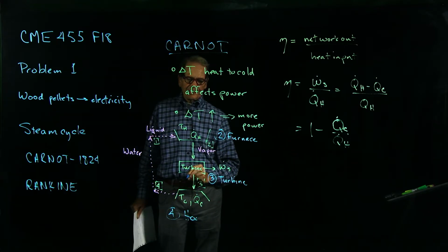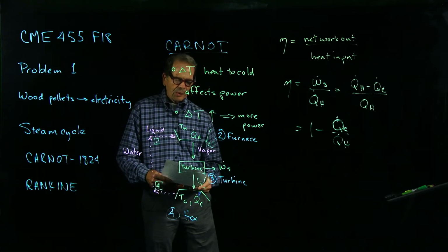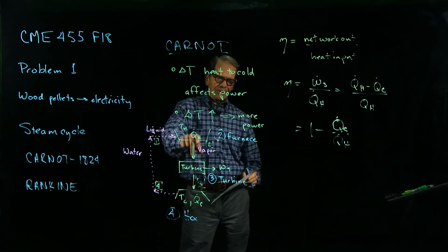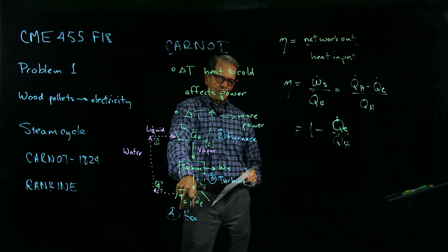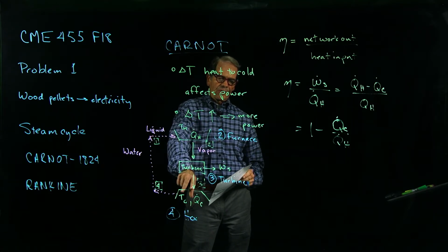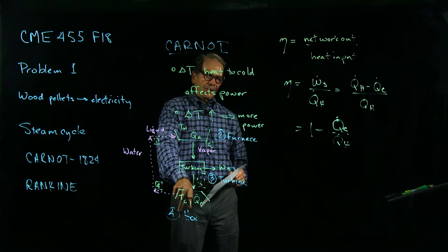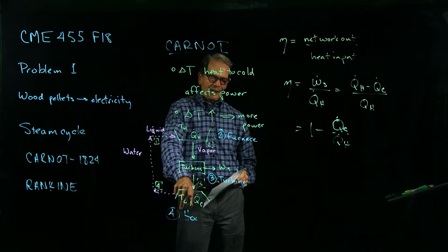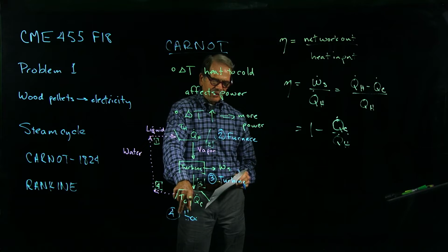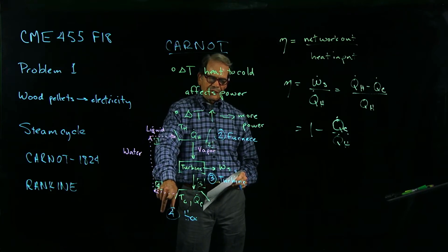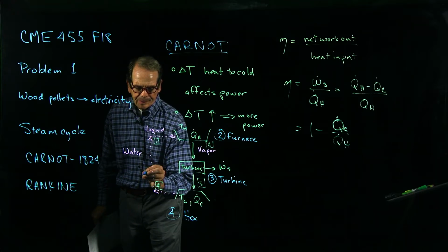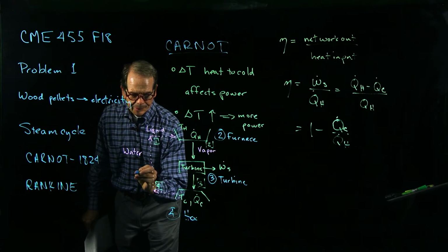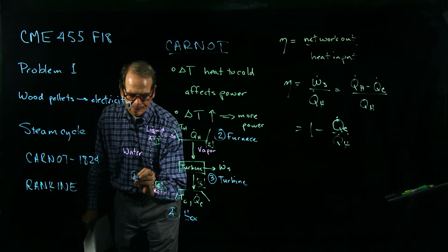That's the heat exchanger. And then what's happening through this process is that we have a high pressure and high temperature here. This becomes a low pressure and low temperature by the time it's gone through the turbine. But it is still a vapor. We now need to condense, when we've condensed it here, it is at a low pressure. We have to increase the pressure. So this is going to be a pump. That's going to be number 1.